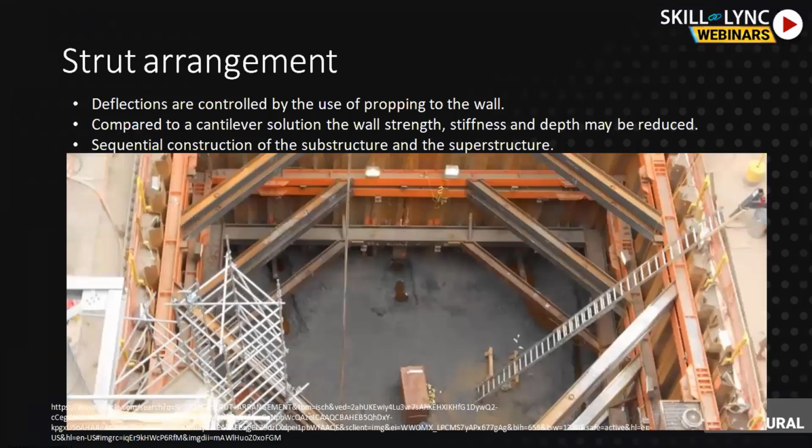So generally for constructing a wall, like sheet pile or soldier pile, these can be used as a cantilever wall for a depth of 4 to 5 meters. Other piles, like secant pile, contiguous pile or diaphragm wall, can be used for a depth of 8 meters. Excavation we can go as a cantilever wall.